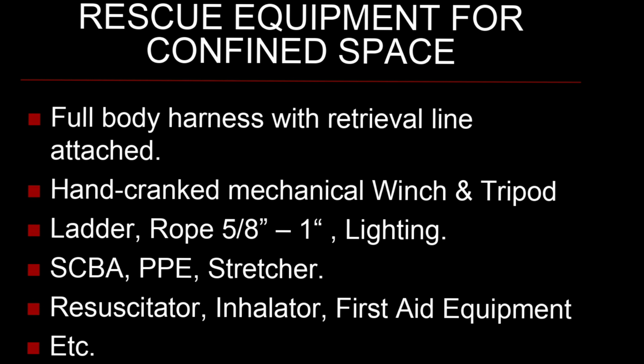Rescue equipment for confined space. 1. Full body harness with retrieval line attached. 2. Hand-cranked mechanical winch, tripod. 3. Ladder, 5/8 rope, lighting. 4. SCBA, PPE, stretcher. 5. Resuscitator, inhalator, first aid equipment, etc.